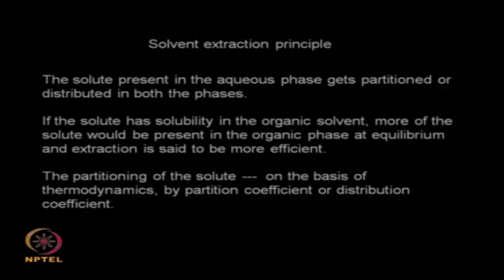If the distribution coefficient or partition coefficient is not so large, you may have several stages of extraction, you may have a train of extractors, and at each stage you will be extracting a little of the solute. So overall you will be extracting the entire amount of solute of your interest.